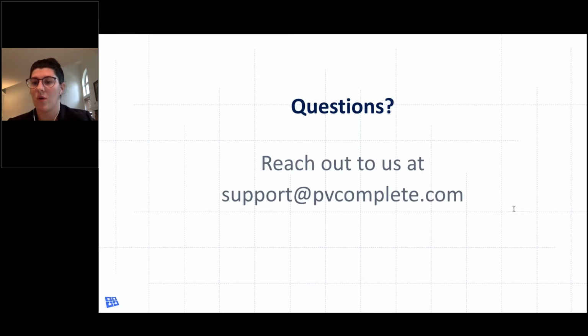One more question, where is the topo data from? So we're pulling from Google Elevation Services in the case of PVSketch Mega. This is an option as well in PVCAD Mega, but again, in PVCAD Mega, because we're in AutoCAD space, there's added flexibility. So we have an additional option specific to PVCAD Mega to import your own topography. So you would import it as you normally would in AutoCAD and then specify the layer so we can find it and analyze it for you.